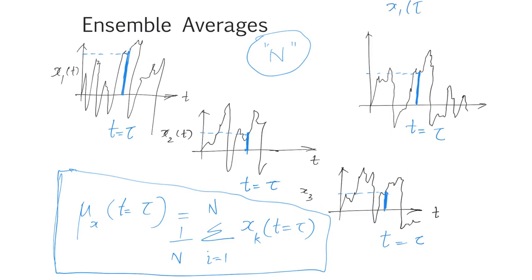x1 of tau, let's say, is equal to 5.02 mm, slightly on the higher side, but for the sake of explanation, let's say x2 of tau was coming around 4.8 mm, as shown over here. For x2 of t, I'm drawing this perpendicular, and this perpendicular is meeting this curve, and then I'm drawing a line parallel to the time axis to compute the displacement of the landing gear in this particular time history corresponding to a time equal to tau.